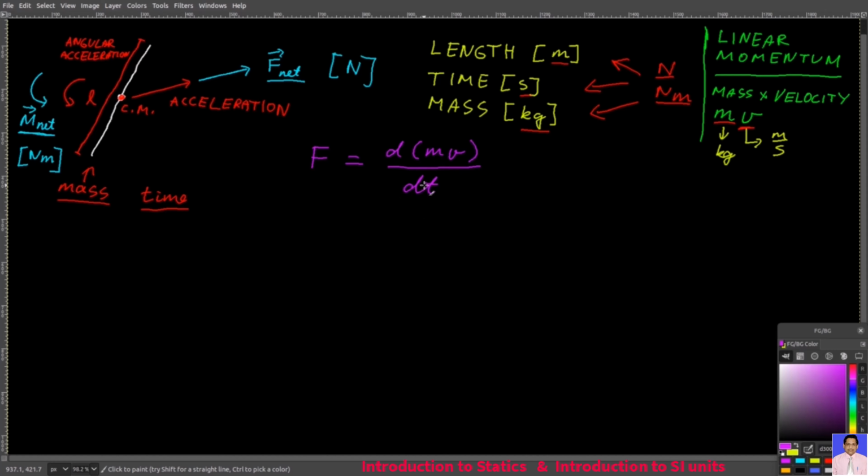And then if you take that force that points in a random direction, let's say here, and let's call its magnitude F, and then if you draw a perpendicular line to this force vector up until this point, and let's call it A, and this line is perpendicular to the force vector, and the length or distance of this line is d, then you have a moment about point A, and it equals F times d.